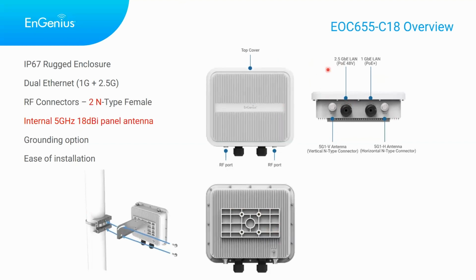So the C18 version, which comes with an internal panel antenna, you would have two N-type connections for radio 2, and then you would have radio 1 dedicated for that 18 dBi panel antenna. So this is a good option for clients who just need a simple bridge without having to search for external antennas. Maybe they just need a simple point-to-point connection, or maybe point-to-multipoint connection as well, and they just want to make use of the device as is.